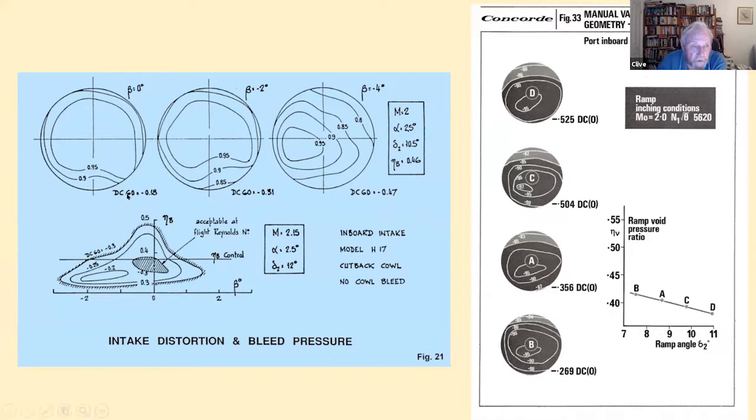This one is called DC60, which is actually the average pressure, if you like, over a 60-degree segment of the compressor face. In flight, we couldn't actually do that because we didn't have the instrumentation. We had 5 inlet guide vanes at the front, so we ended up using a closely related parameter, which was DC naught, which was just the conditions along any one of these 5 vanes.